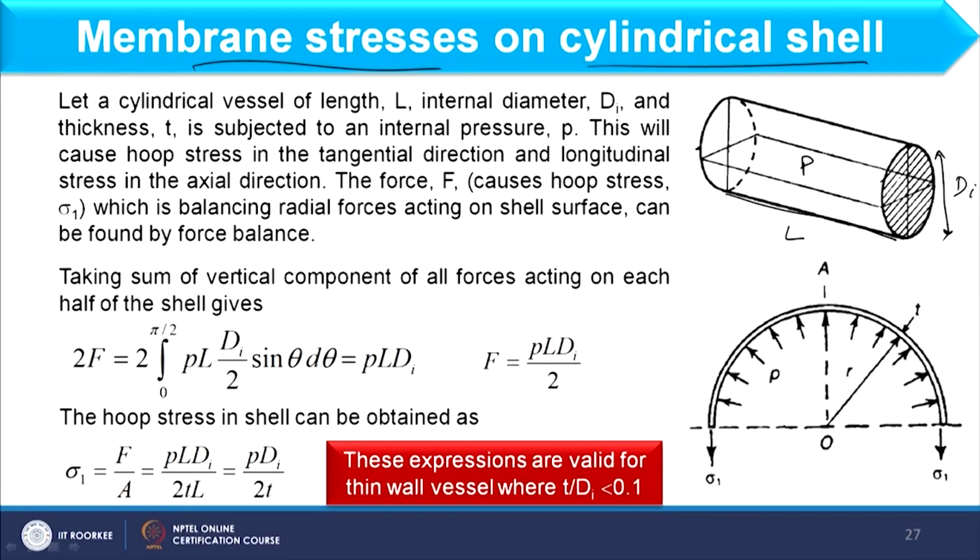So, when internal pressure acts, some stresses are formed, and these stresses are usually available along the length and around the circumference, okay. Because of internal pressure operation, we have two stresses, one is called hoop stress and second is longitudinal stress in axial direction, okay. So, to derive the expression for how we need to calculate thickness, we will make the force balances around the object, but before force balances you should understand what the stresses are. As I have told, there are two stresses, hoop stress as well as longitudinal stress.